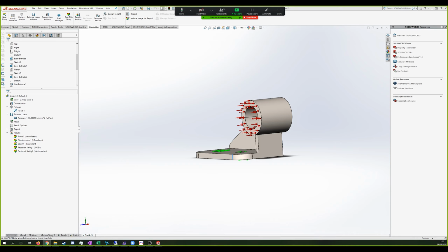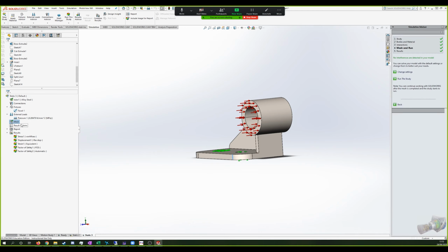Why have you got 6.8? Did you convert it? Yes, I did. Fair enough. The location of the max stress is in that little corner. That's where I expect. So when you're looking for a singularity, you always want to check the same spot. So you're looking at a point of interest, not wherever the max is. It should be that corner. It's just above the corner. Yes. Now, is it just above the corner?